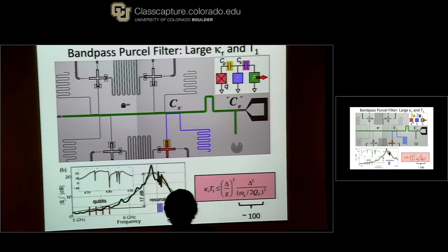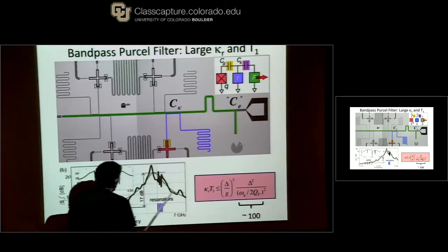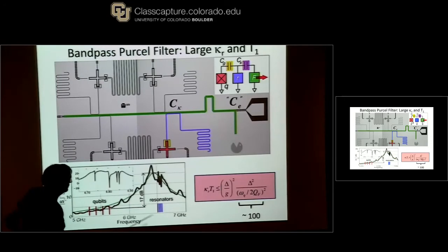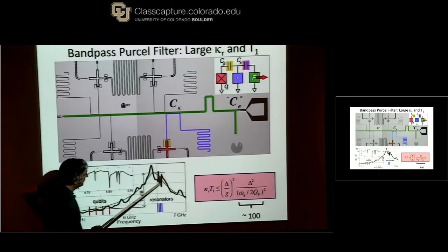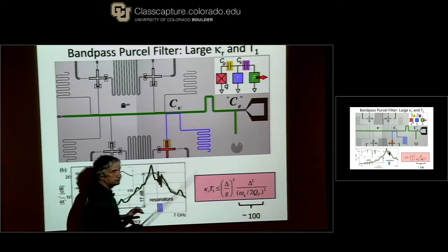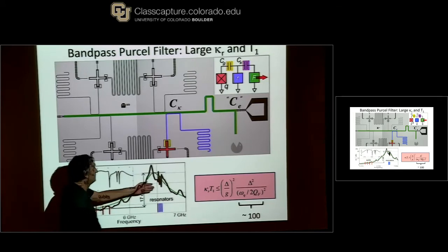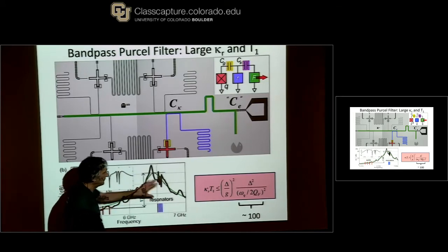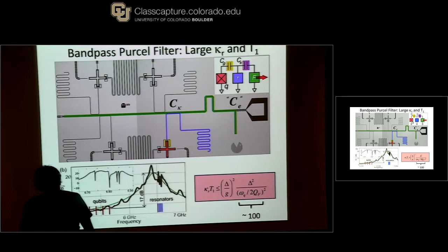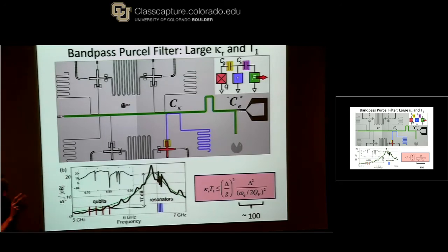We could do a higher Q filter here, and a higher Q filter would work, but we want to make sure that if we make that too high, then we're going to slow down the readout of photons from the resonator, from these resonant modes. So we don't want to slow that down too much. But it turns out this kind of Q could be designed better, but this is just very safe. It's not too hard to do. But one could optimize that some more.